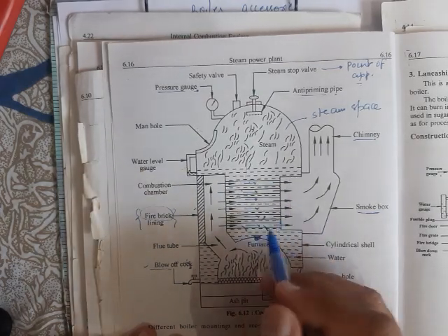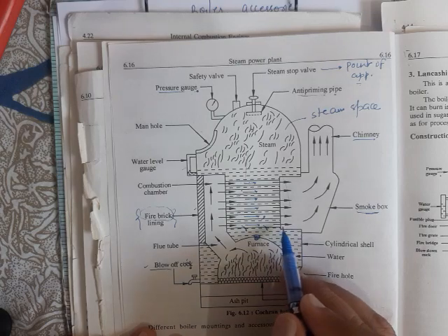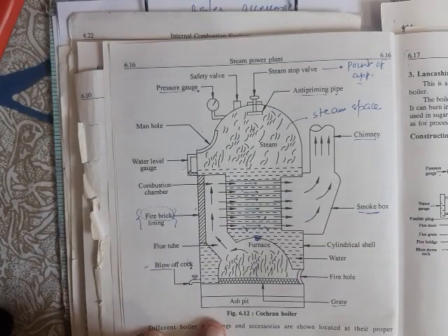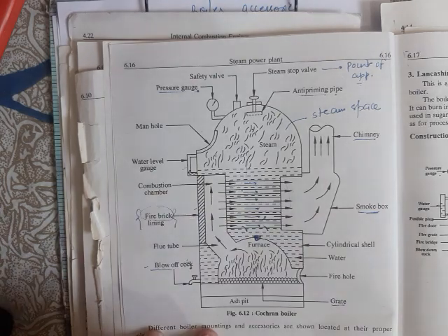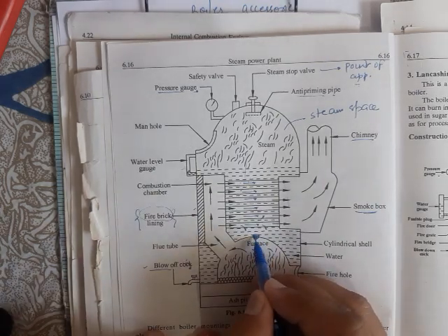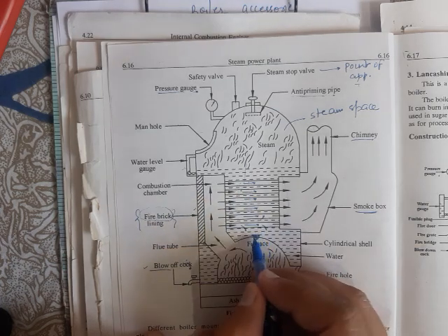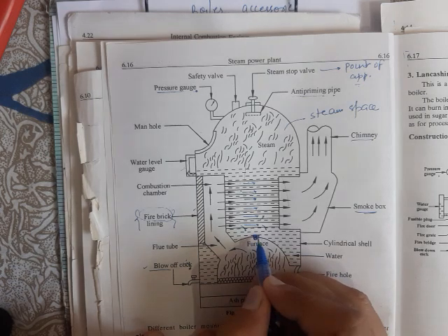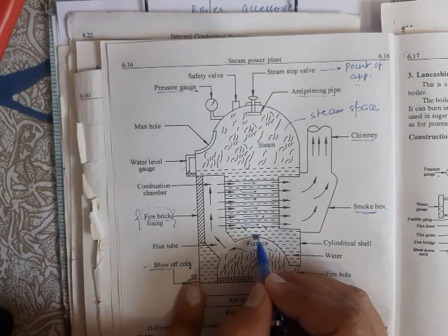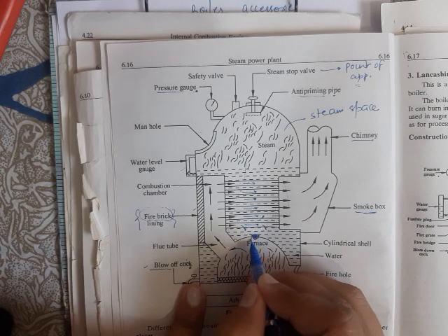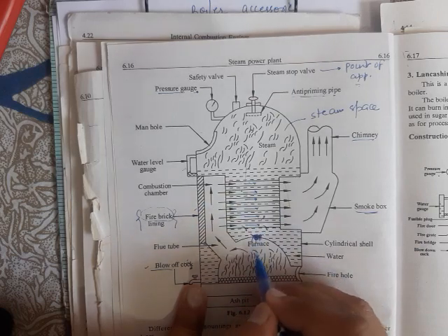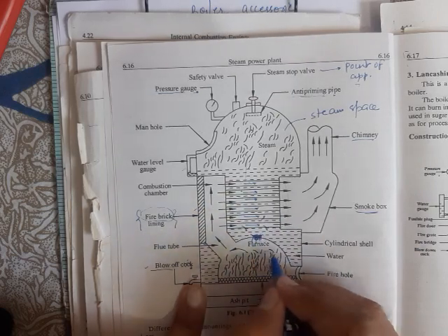And as a result of this, the other important components of the boiler start getting overheated. As a result of that, an explosion may take place. In such a situation, to avoid such a disaster or accident, a fusible plug is there, which is made up of gunmetal. When the temperature of the other important components of the boiler increases, firstly the fusible plug melts. As a result, an opening is created over here and the water flushes into the furnace and brings the fire to extinguish.